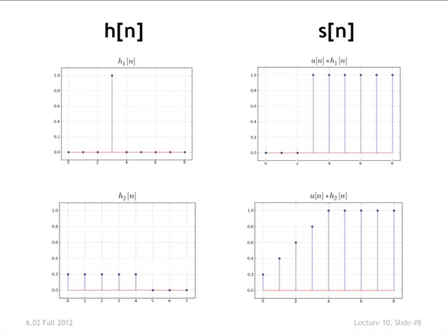And so what you expect to see in the step response is a transient and then it settles down. The difference is in the step response, it settles to another value. It doesn't come back down to 0. So when this comes back down to 0, what this has settled to is sort of the integral of this. It's the area under this. But we're talking about discrete time functions, not continuous time functions, right? So the value that it's settled to here is the area under this. So the duration of a unit sample response gives you some feel for how long a transient lasts. If you've got a channel and you hit it with an input, you know that the transient will last about as long as the unit sample response lasts. So the transient in the step response shows that clearly.